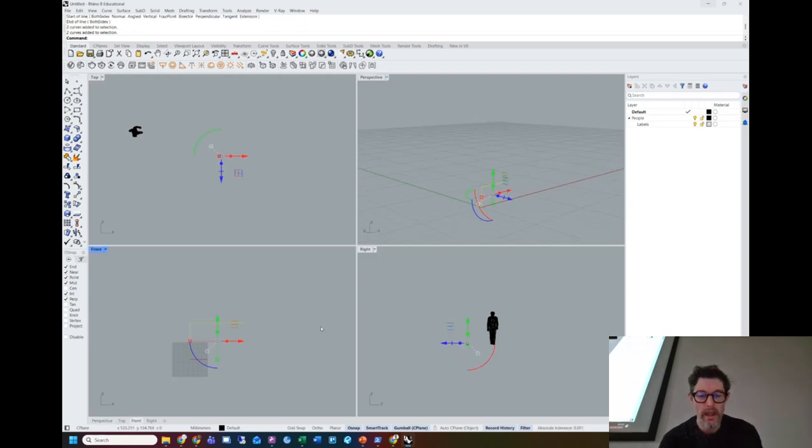Now, what I'm going to say is, I know I have to go from a floor that is a certain height above the ground to a floor that is another height above the ground, and I can do a quick calculation to work out how many meters that is. Standard distance between floor to floor might be something like 3,000 millimeters, 3 meters. So I can grab a calculator and go, how many stairs do I need? If each stair is 150 millimeters, and I need to travel 3,000 millimeters, well, it's pretty simple.